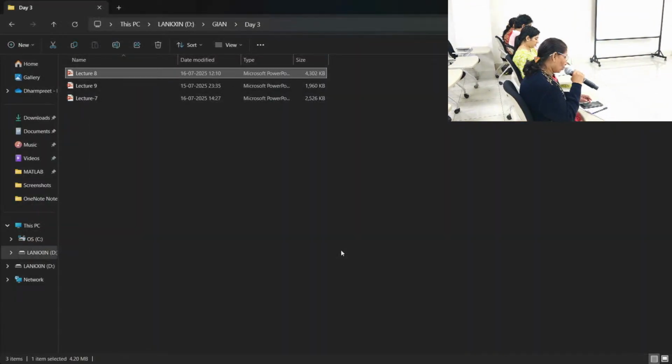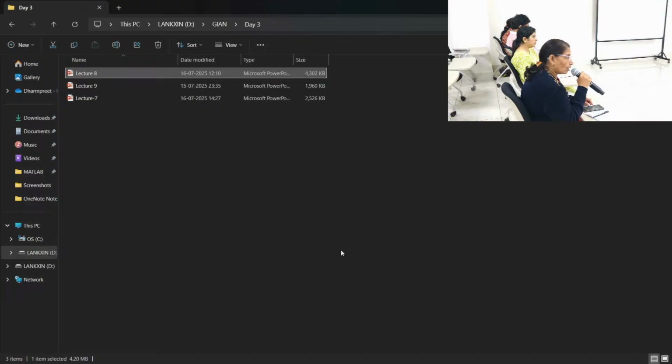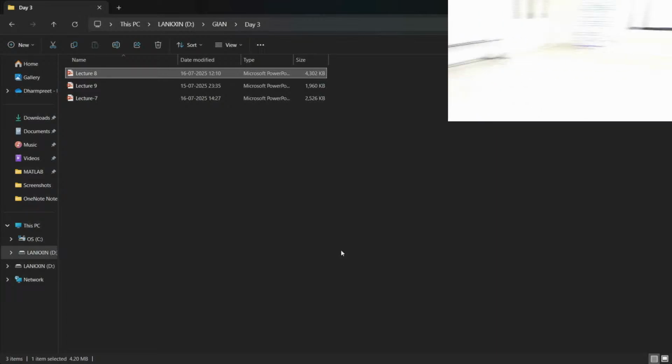There is one question where you showed one case study, a 15 kilowatt grid connected converter. In that, the grid impedance you have selected is 4 millihenry and resistance 0.2 ohms. Sir, how did you select these values? Because we say the grid is an infinite one. Yeah, for testing at least.